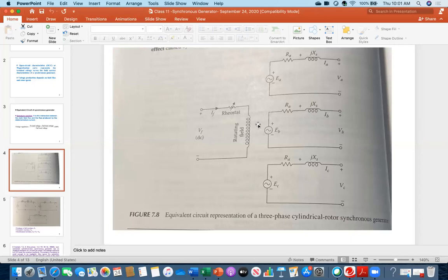And the rotor flux is called the main field flux, because at the beginning, when no current is flowing, this flux is present. This flux is always present because it is needed to build up this voltage. Once the voltage builds up and you connect the load and current starts flowing, that produces another flux here, and that flux opposes or interacts with the main field flux, ultimately reducing some of the main field flux. That phenomenon is called the armature reaction.